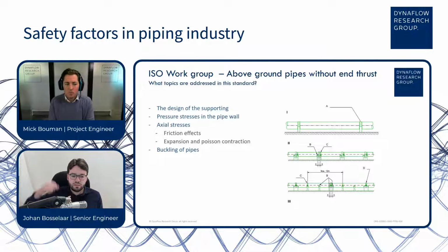Is it relevant to use steel, for instance, for these kinds of piping, or is it mainly just the fiberglass piping that you just talked about? You could use steel, but that has its specific problems related to corrosion. In this case, the use of FRP materials is normally quite a bit cheaper, because you can install them and then you won't have to replace them for about 50 years. Steel would be a bit more expensive, because you would have to use specific alloys that are capable of dealing with